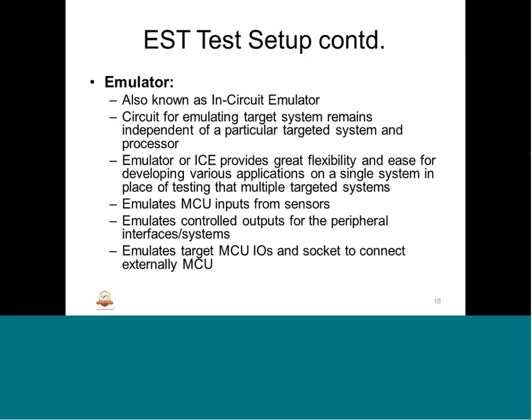So what is an emulator? It is also called an in-circuit emulator, ICE. Basically, it takes the in-circuit values and provides the user a gist of what values are going on with the target, so it actually emulates what is needed. Similarly, the user can put values into the registers with the help of emulators. The circuit for emulating the target system remains independent of a particular target system and processor.